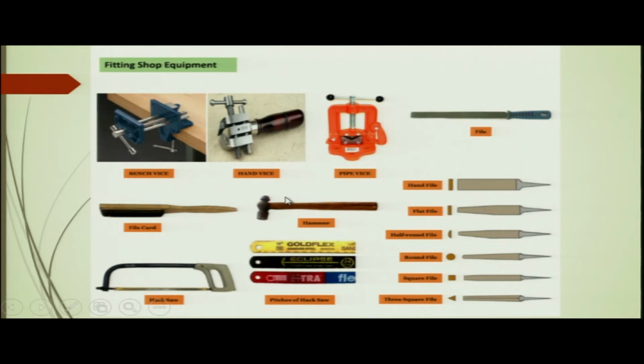All right. Now, this is the pipe vise. Pipe vise is also very popular. You can see on the roads where the workers are cutting the pipes or making thread on the pipes, they have to be mounted on the vise, so that there is no movement of this with respect to the tool that you are using. So, here also there is a lead screw. This is the housing of the vise. This is fixed bed, and this is movable. Okay. This is movable. This is rigidly attached at the end of this lead screw.